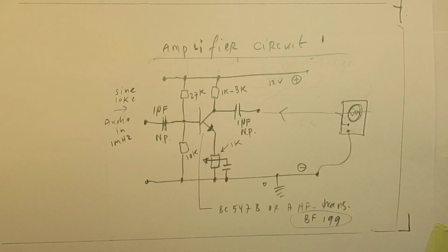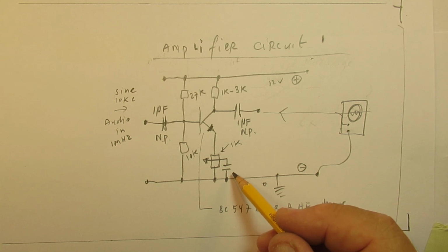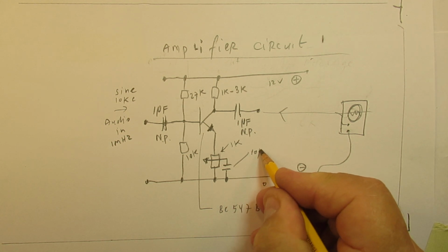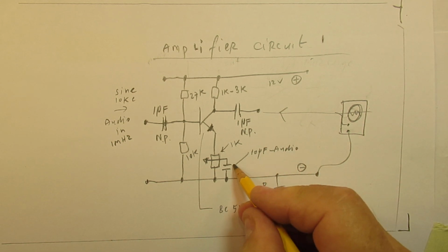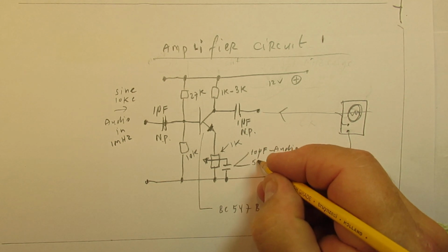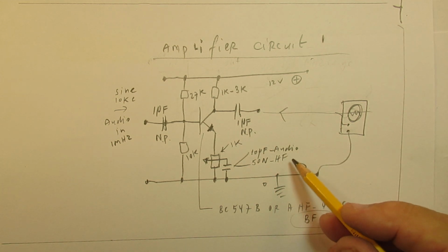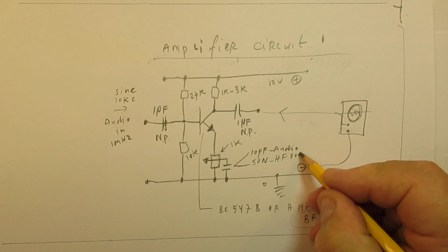That depends completely, the amplification, the frequency band where that works, depends completely on the value of this capacitor. So it's 10 microfarad for audio, it's say 50 nanofarad for high frequencies, and then I mean not too high, but approximately 800 kilocycles maximum.